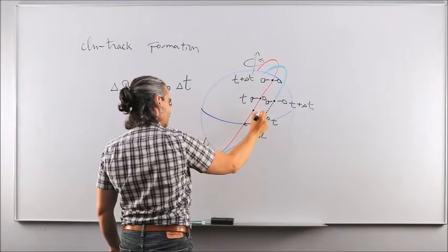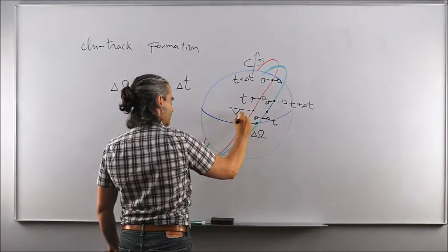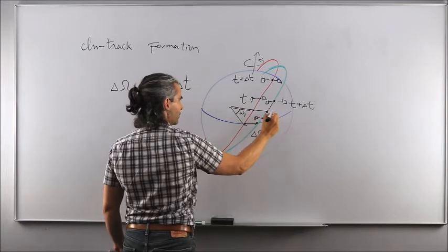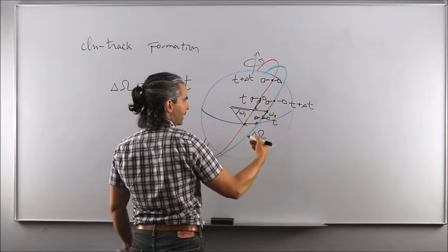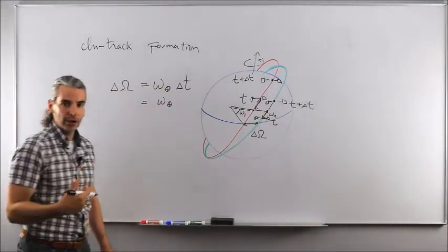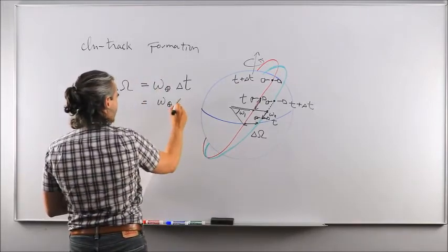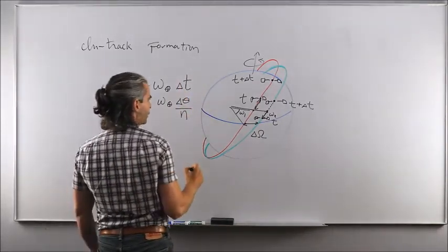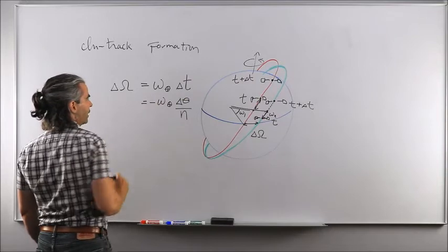Okay, so say perigee is here, perigee is here. So that is argument of perigee spacecraft 1 and argument of perigee spacecraft 2. So they would be the same. Yet you want a difference in true anomalies, meaning that the chaser spacecraft needs to be ahead or behind the target spacecraft to make sure that we take into account the rotation of the Earth, and that delta true anomaly is related to the delta time just by the n factor, and because of the convention to measure delta true anomaly, we're going to just put the minus sign here, okay?